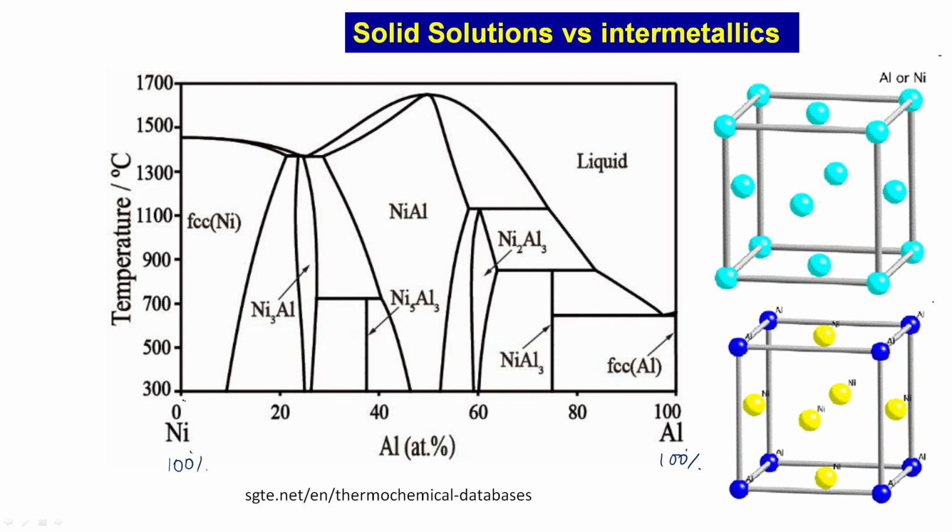So, this is what you can add aluminum into nickel, still form a solution, and solutions are marked by this. So, when you see a small bracket around a metal atom, it is called a solution. But other than that, on the right side you have also aluminum solution, but very minute quantity of nickel can go into aluminum. On the other hand, large quantity of aluminum can go inside a nickel. So, there are reasons for it, let us not talk about it.